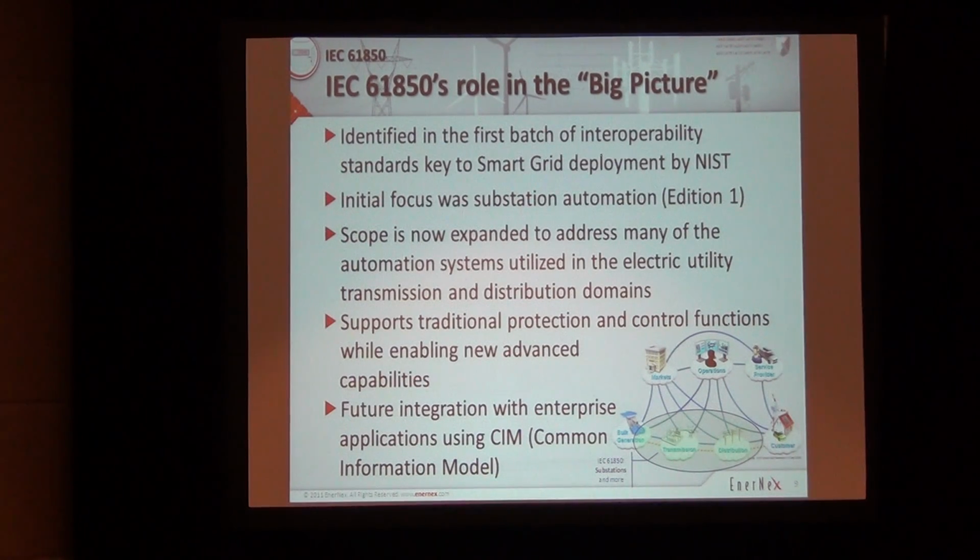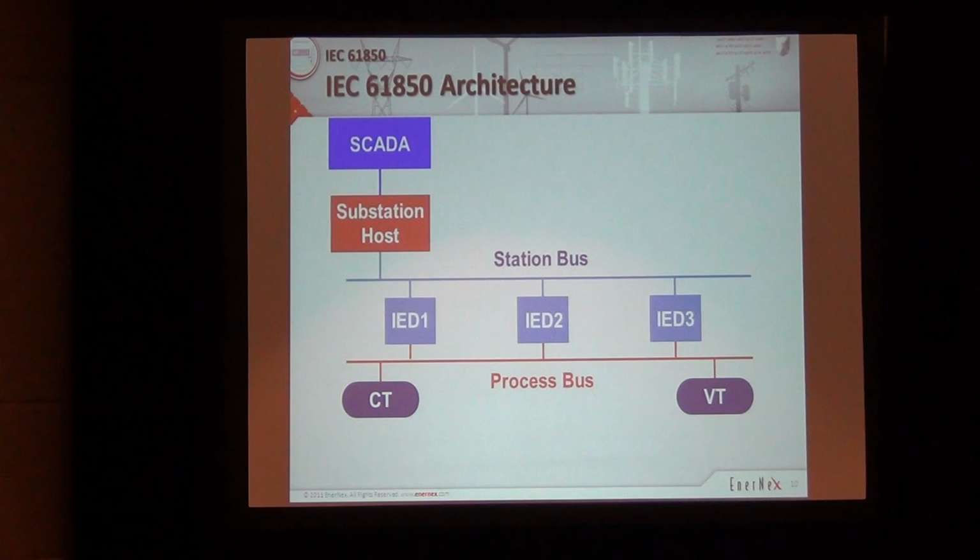So the long-term vision is we come along with a new device. I'm way oversimplifying it, okay? But we are able to connect it into the network, and that device, through publish subscribe, the data will be available to databases throughout the system, including at the enterprise level. So it significantly impacts and benefits not just the substation work and engineering associated with it, but the whole system. It's a very big story when we look at it that way. This is a significant oversimplification. I've got another diagram in a minute of what we're talking about at the substation level, where we've got a SCADA system at some remote location or multiple enterprise users, a substation host, or what might practically speaking be a PC.